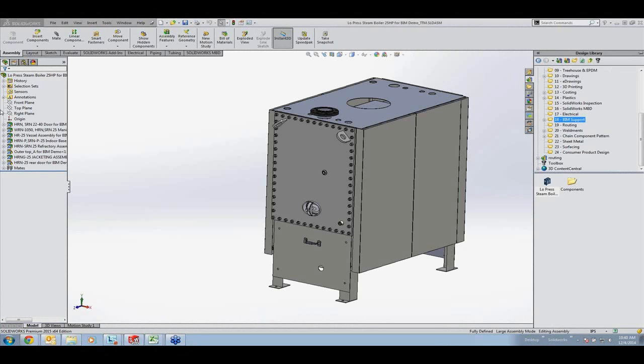Now there's a second type of routing that SolidWorks now supports. In 2015 it's called the cable tray. Cable trays are kind of tricky because they have an open component. So you see here that it's an open U shape. So again, I'm going to start the route just by right-clicking and clicking on Start Route. Cable tray, and I have a 90-degree elbow there as well.